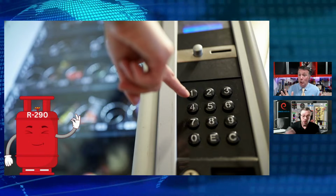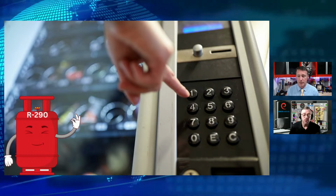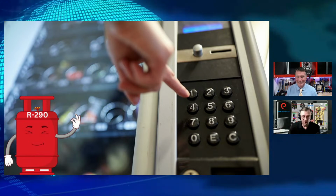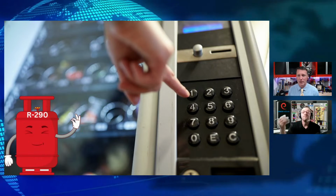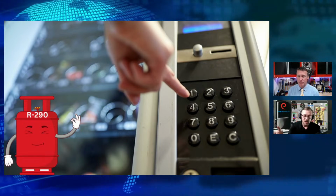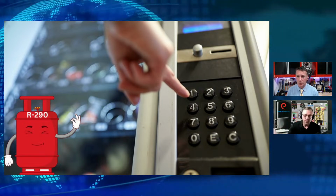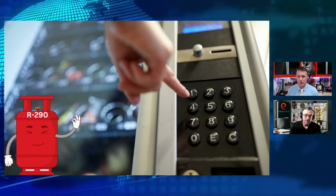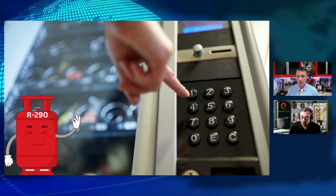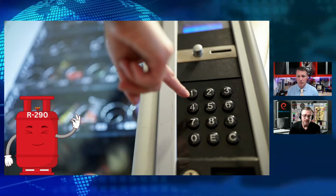There are some locations that say, listen, if you're working on this A3 highly flammable refrigerant, you can't do it here. Exactly. The building code says, listen, you've got to come pick it up in your truck, take it outside, wherever, fix it, and then bring it back. But you can't work on it in this location, in this building occupancy, or this classification of it's a commercial kitchen. There's open flames. There's a flat top grill. And again, that varies by location, geographic, what building codes are locally. There are a lot of places that say, listen, you can't service it in place. Come pick it up, put it in your truck, take it away, fix it, and bring it back.